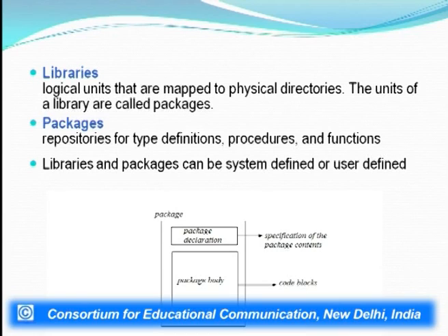Then the libraries, these are the logical units that are mapped to the physical directories. The units of libraries are called packages. So packages are basically the repositories of the type definitions, procedures and functions which are predefined, and they can also be user defined. A user can declare his or her own package, and certain packages are already inbuilt in the libraries that are provided with the VHDL system.